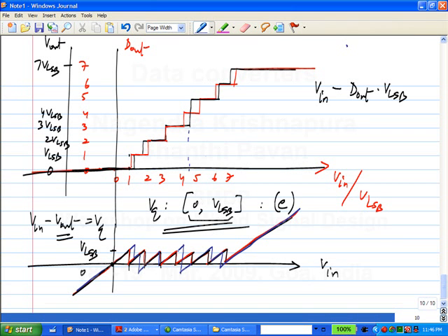Okay, it is different, that I know, but what is the problem? Exactly. The range is more than 1 VLSB. Okay, that is the problem. So far along, we said that the range of the quantization error will be 1 VLSB. It was minus half VLSB to plus half VLSB or something like that. Now the range has become more than 1 VLSB.